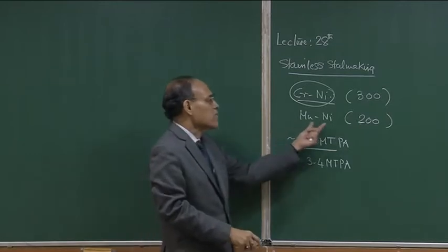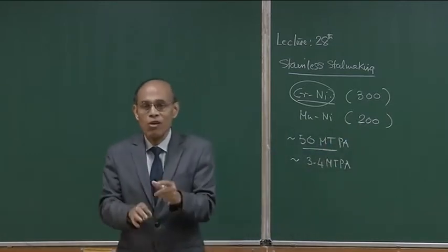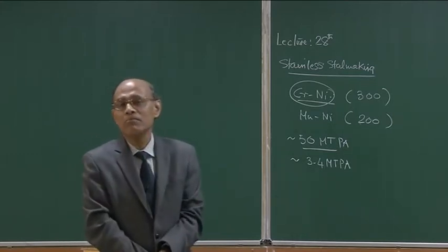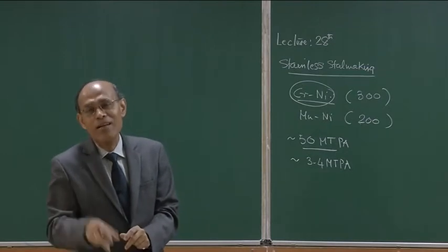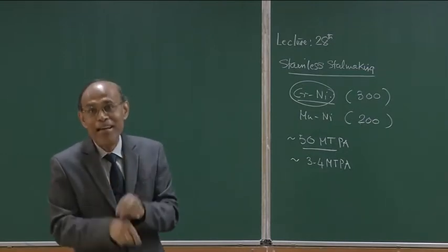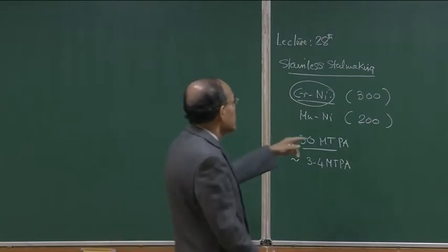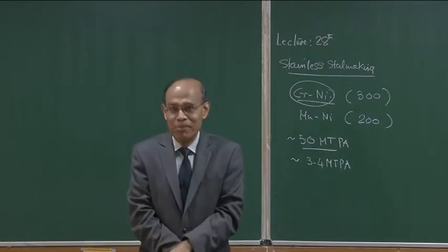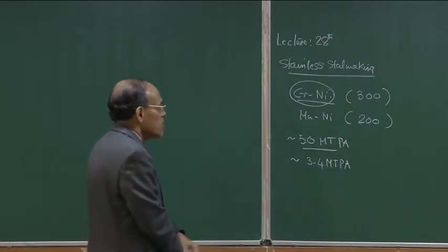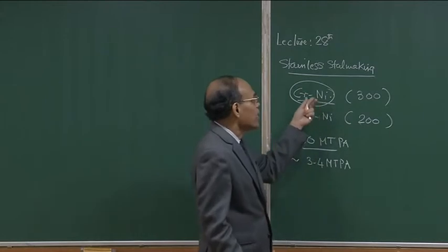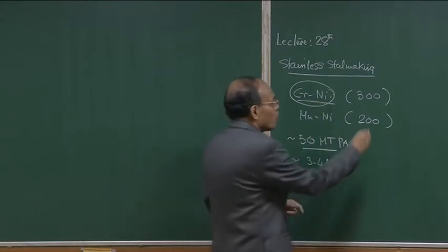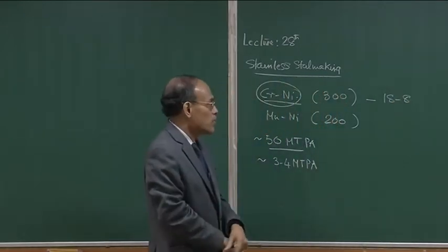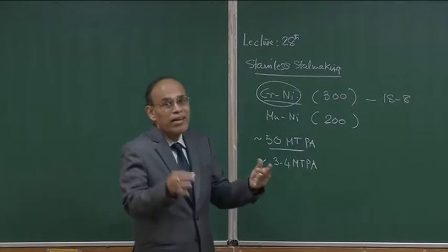this stainless steel is not so good. Most of the time, it is a little out of context here, you may have seen that there are many stainless steel artifacts, particularly kitchen utensils, which tend to develop cracks, and those are from the 200 series, where nickel is replaced by manganese, and the deep drawing quality of the material suffers as a result. So, this is a cheaper variety, and as the content of nickel increases, we mostly talk about 18-8 austenitic stainless steel, where 18 is chromium and 8 is nickel, but there are diverse grades.